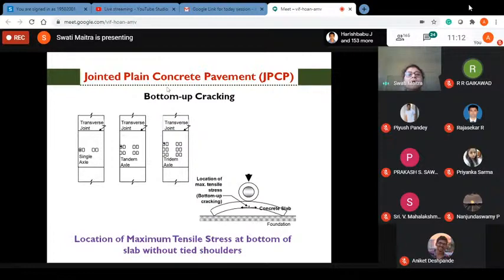Small ni is the predicted number of load or temperature differential cycles for the ith load group during the specified 6-hour period, either for daytime or for nighttime, and capital Ni is the allowable number of load and temperature differential cycles for the ith load group during the specified 6-hour period. So combining these two effects is the cumulative fatigue damage. That should be less than 1. So the pavement should be safe against fatigue if this total effect is less than 1.